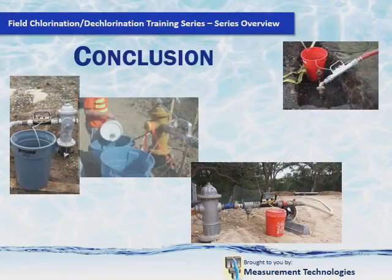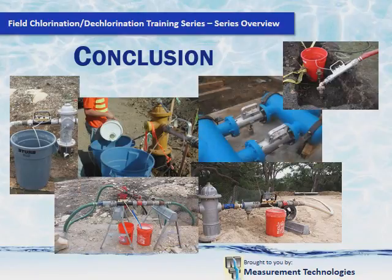The H2O neutralizer is the only device currently available to both chlorinate and dechlorinate, with flow ranges from 9 gallons per minute to either 1,250 for the 3M device or over 4,000 gallons per minute for the 5M device. This is the only device that can be connected to service lines as small as 3/4 of an inch and still give full performance. Future training programs will give you all the details on how we can save you money and time using the H2O neutralizer.